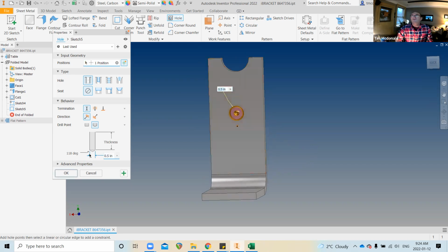And how big is that hole? Well, okay. So under this tab here, I'm going to put in hole. It has to be an underscore. You cannot use a dash here because a dash signifies a mathematical operation, subtraction. Hole_diameter equals 0.5. So I'm relabeling my parameters as I go.